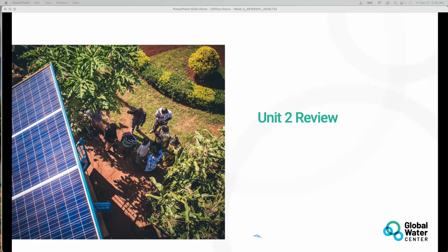yield of the borehole, so that when you install and operate the system, you will not face a problem of water shortage in the future. But 72 hours is still not enough, because we will use the system for 20 to 25 years. So it is still not enough, but relatively it is better to increase the pump testing hours.